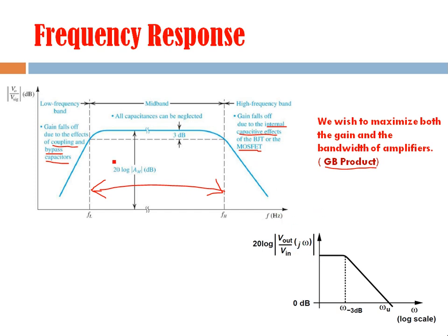So in that case we will not see this kind of decrease in the gain at low frequencies. You can see here one example of frequency response in case of differential amplifiers, which are direct coupled amplifiers: starting from 0 frequency, gain is constant up to this particular value of frequency, and beyond this the gain starts decreasing, as it was decreasing in the high frequency region.